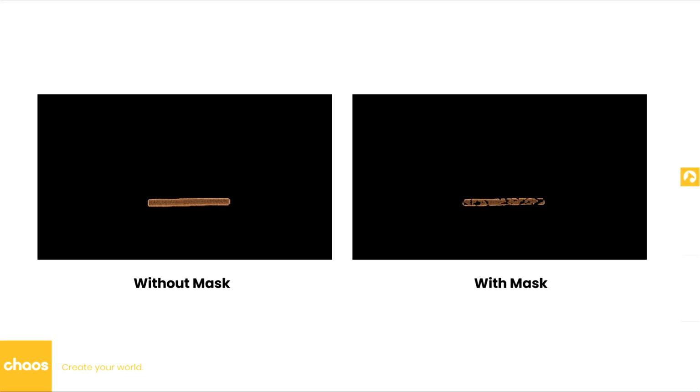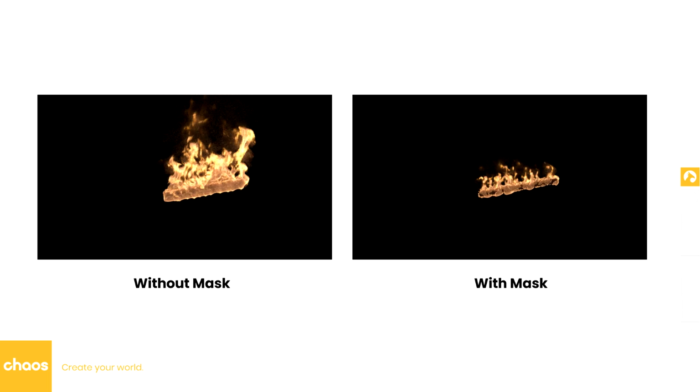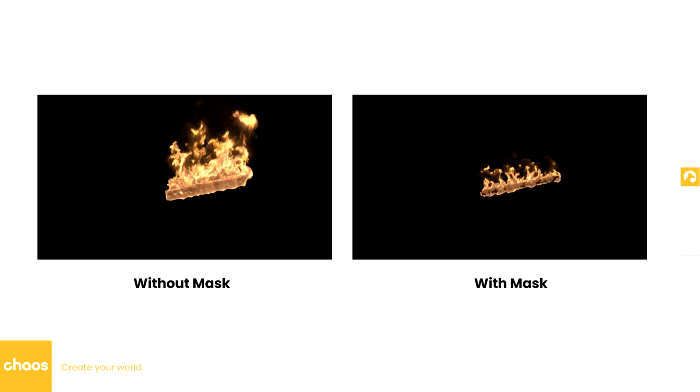Here, I have created a simple animated cylinder as an emitter, as a simplified version of the tower. So here we have results of emitting fluid with and without adding a mask in the outgoing velocity of the source. To be honest, the one without a mask looks more convincing, since masking the emission reduces the total output of the fluid and makes it appear weaker. However, we can fix this by switching to a different conservation method later. Just keep in mind that using a mask in a source can improve realism.